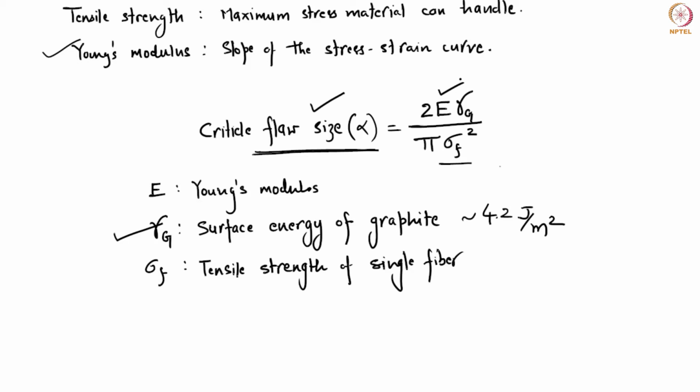What does that mean? That means that if you increase your pyrolysis temperature and you get the Young's modulus that is very high, you may actually also get larger voids in it. This relationship, however, may not be valid for ultra thin fibers, because there you have defects annealing out very easily. However, if you have 1 micrometer to 5 micrometer diameter fibers, which is often the case with industrial carbon fibers, indeed you may get some defects when you increase the carbonization temperature.